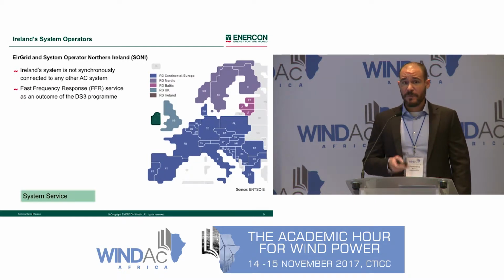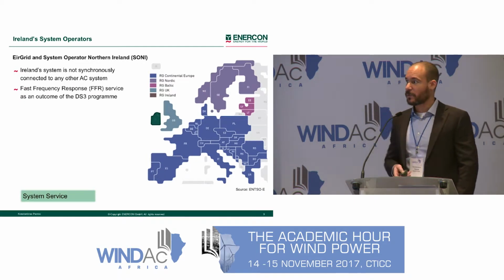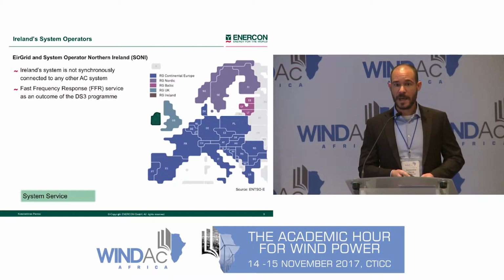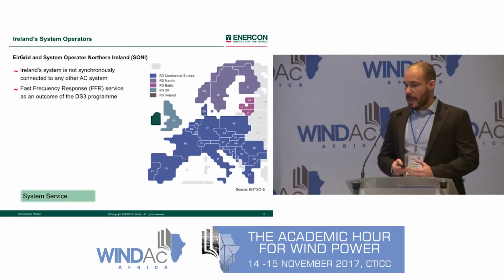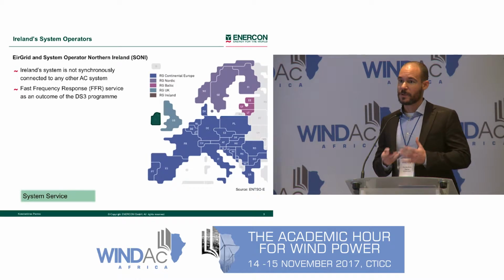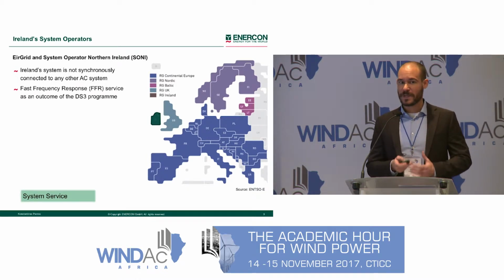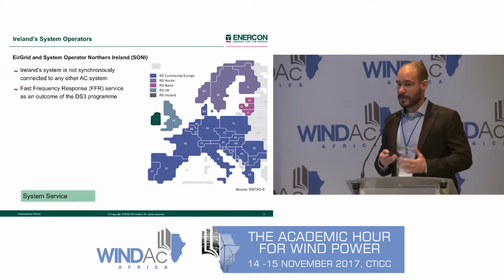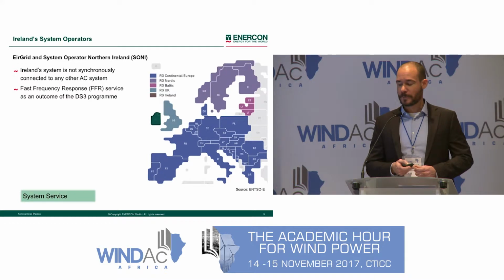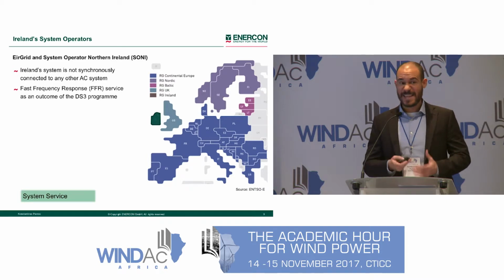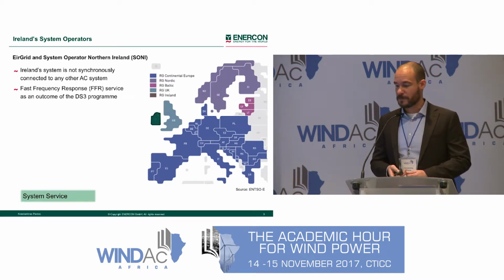One of the key findings of the studies performed by the system operators of the island, SONI and EirGrid, in order to facilitate the transition to renewable energy, was that non-synchronous renewable generation could be reliably integrated with instantaneous penetrations of up to 75%, if, amongst others, a set of changes would be implemented, amongst which we have the so-called DS3 system services.